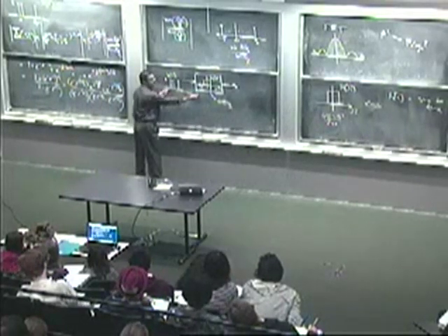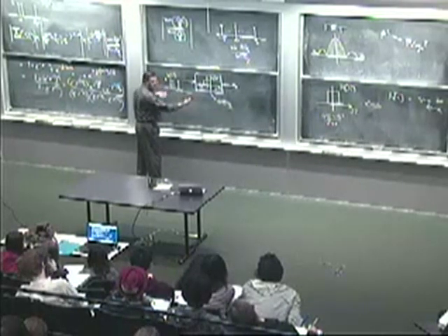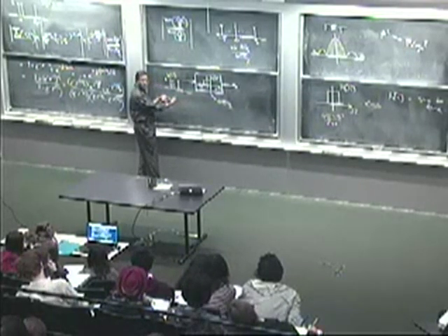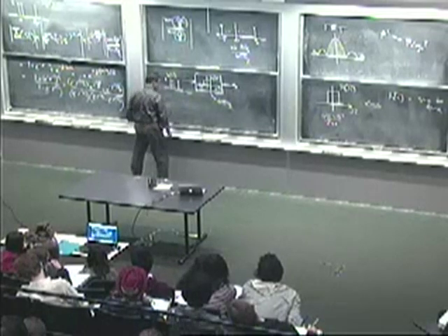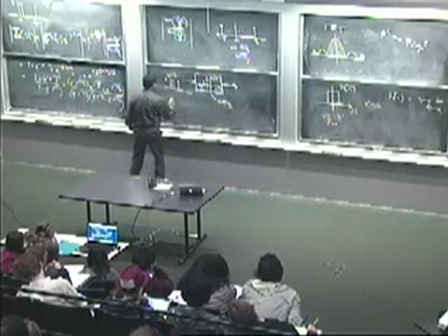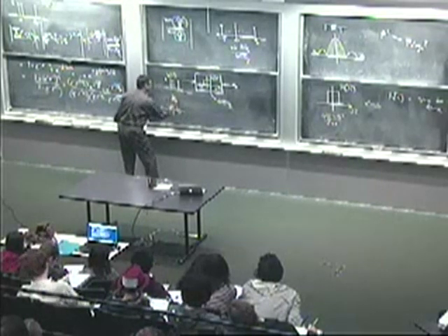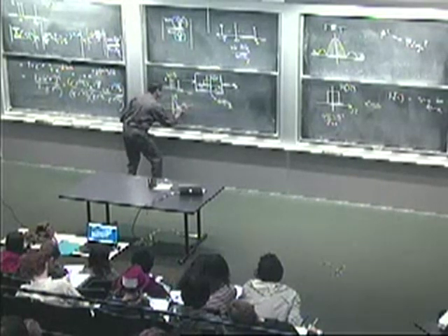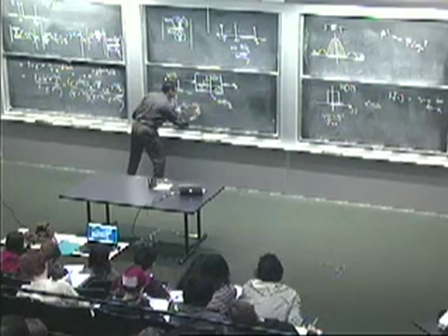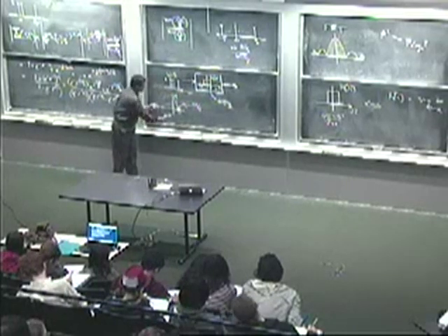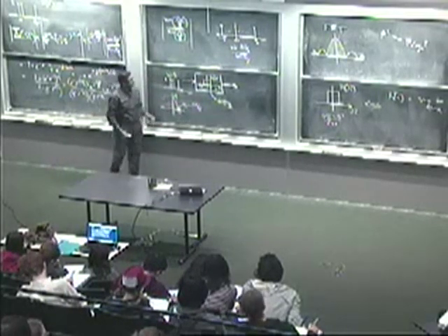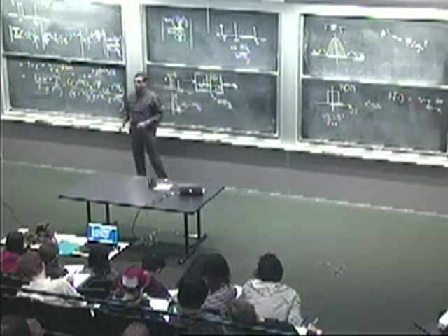You see, if you make n longer, you make the pulse longer, you shrink this correspondingly in the frequency domain, right? We said that on these sinc-type characteristics, the height was n. This first null was 2 pi over n. Make the pulse longer, you pull the main lobe in tighter, and more of this is going to go through.